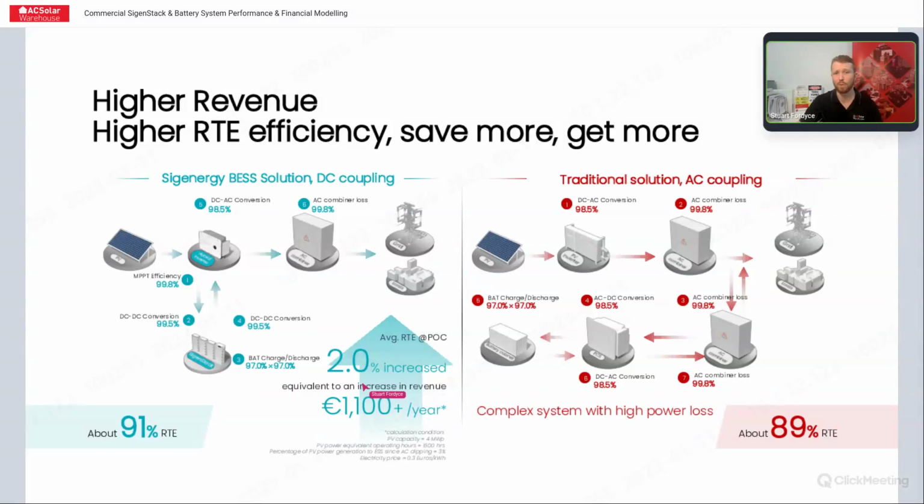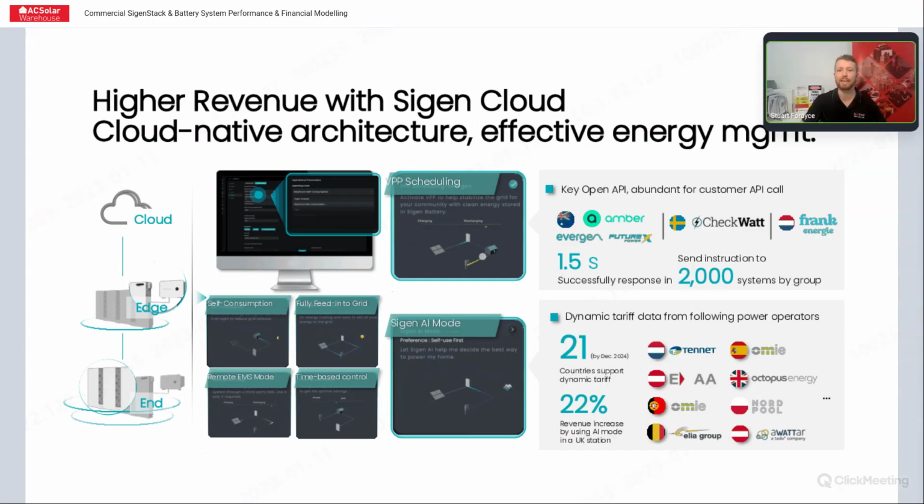On average, you're looking at probably a 1 to 2% gain in energy usage, and you're also looking at minimizing the amount of clipping you're getting from your DC array, particularly when you're scaling up to 1, 2, 4, 5 megawatt systems. These small percentages can really equate to some serious dollars. And that's what's quintessentially really exciting about the SigenStack product, that it enables us to start taking those benefits to larger systems.